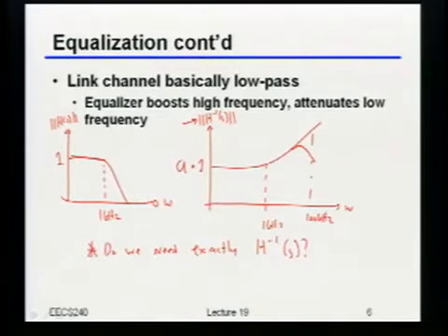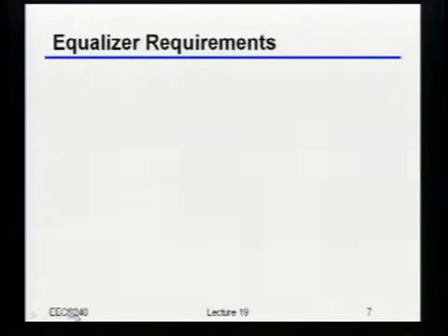So as a reminder, what is the point that we actually care about? How high of a frequency do you think you need to go to? Close to the bit period. Okay, close to the bit period. What was the rough rule of thumb that I gave? Yeah, 2/3 of the bit period, right?